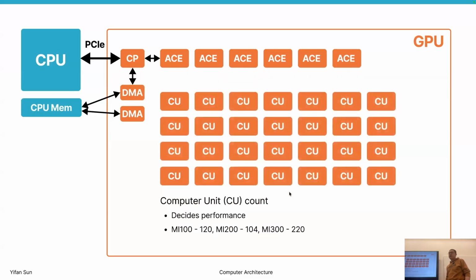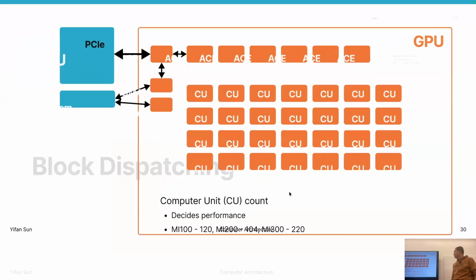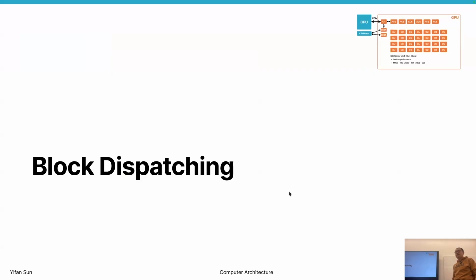If we evaluate how powerful a GPU is, we evaluate how many compute units or how many SMs are there. NVIDIA SMs are slightly more powerful than AMD CUs, but at the same tier of product, AMD typically has more compute units than NVIDIA has SMs. So theoretically, there's no good or bad comparison between AMD GPUs and NVIDIA GPUs. If they're roughly the same tier, their computing power is similar. Sometimes AMD may have even higher computing power.